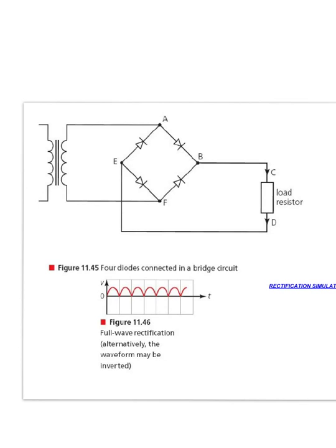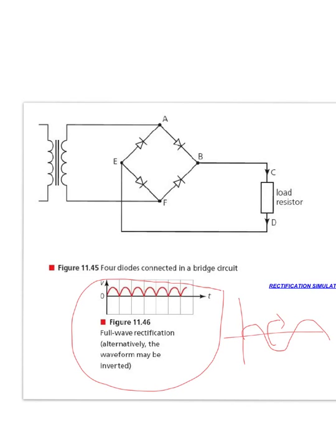Now, what we're going to aim for now is something called full wave rectification. Instead of losing half the wave, which is half the energy basically, we're going to try and get the negative side of the curve to register and flip up to the positive. And what we've got here is a diode bridge circuit. It's an excellent little arrangement and very clever too. Now let's have a look at how it works.